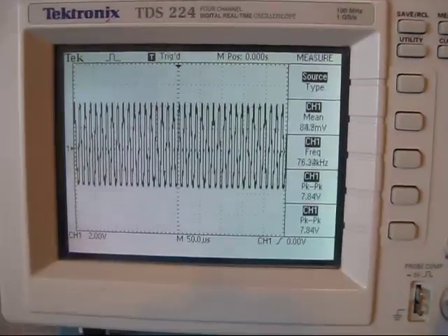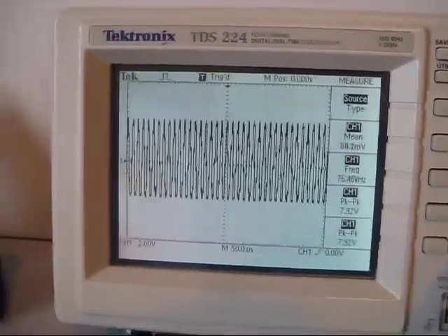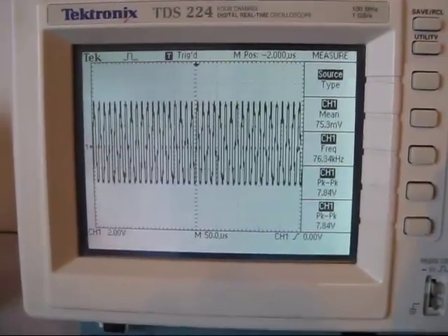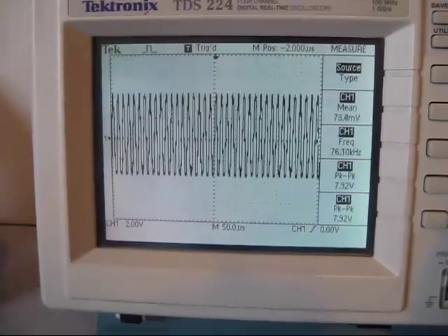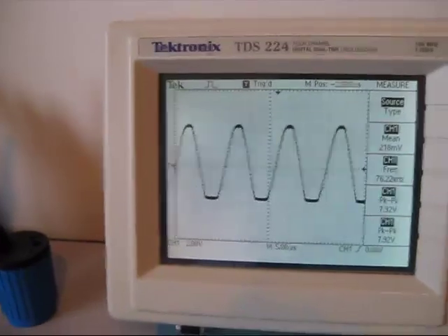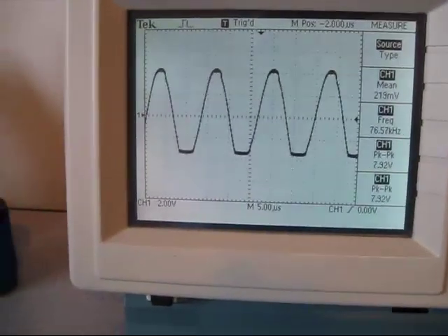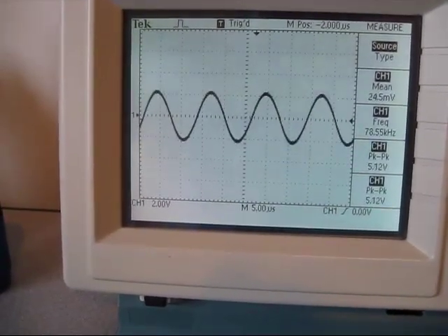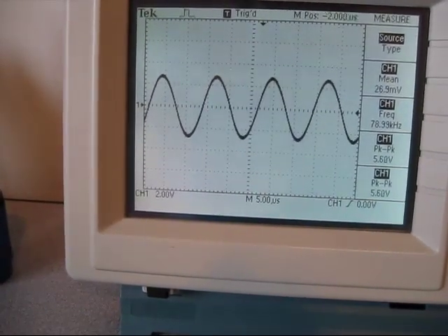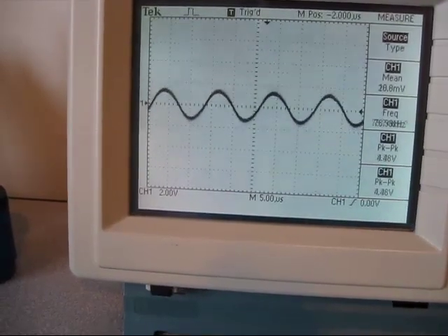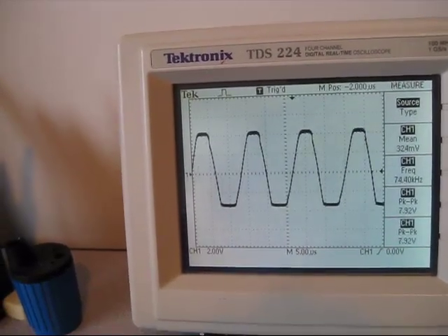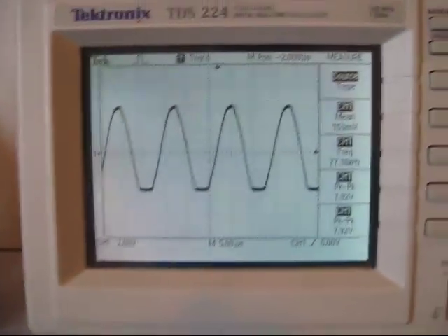So here we go. I haven't changed the horizontal time base there, and we still actually have that 47K resistor bypassed. I haven't changed it yet, so it's only the potentiometer that's helping tune the gain. So we zoom in a little bit, and if we just play with the pot and don't actually reintroduce that one, you can actually get it pretty decent just with that alone, but it's really finicky, of course, because all of a sudden you're going to cut out nearly all the gain. So let's re-include that back in, just so we get some finer control.